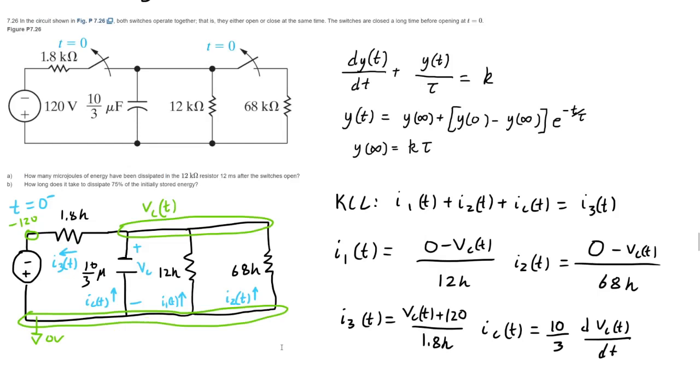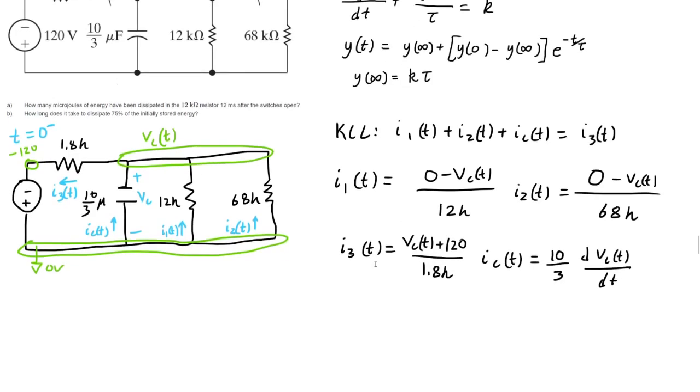In this one, we've got 2 switches, but they work just like the other switches. It's just that these things are going to shut off both sides of the circuit at the same time, leaving us with this middle section. I went ahead and wrote out the equations already, but all we really need is to find this VC(t). To do that, we can just put these two in parallel and solve for it. Or we could write everything out, and I'll just do that on the calculator. That'll actually work just the same.